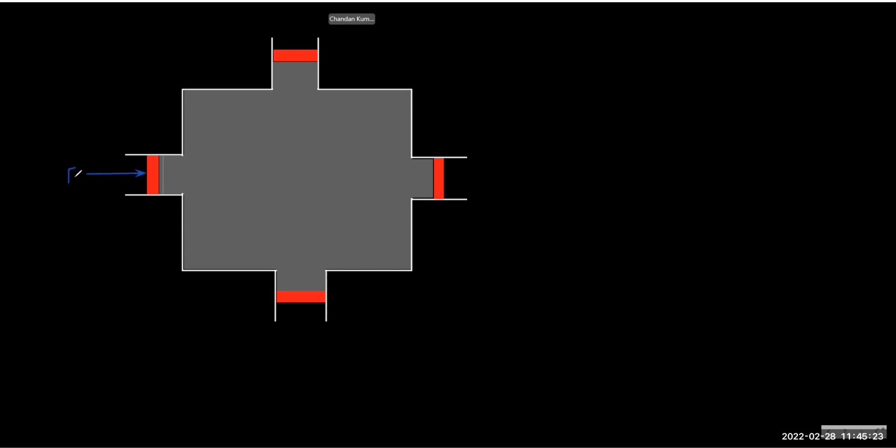By applying force here, we create the extra pressure of F by A. So without your knowledge, the pressure will reach here also. It will reach here, and it will reach here. So you are creating it at one point, but it is not confined to that point. It is going everywhere else, and because the pressure is reaching here, to stop this piston from moving, we have to apply how much force? F, because it's the same area.